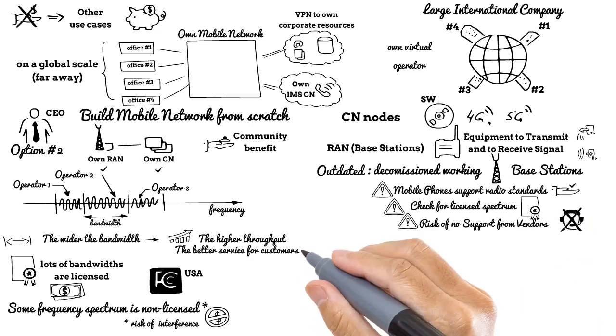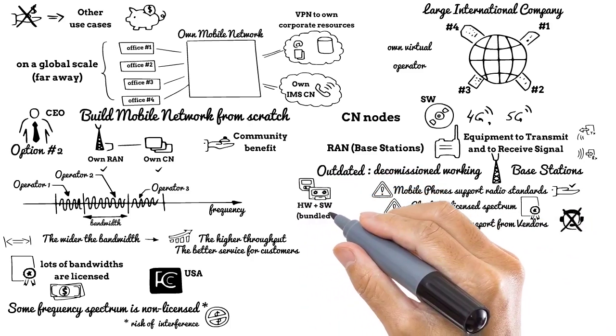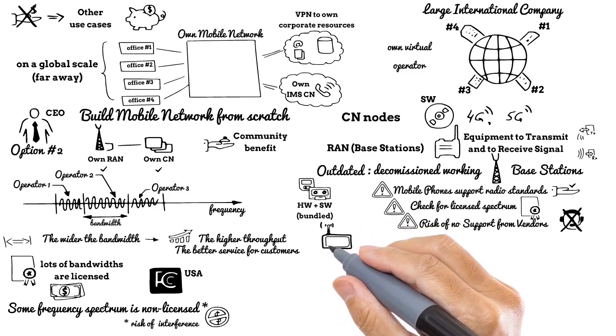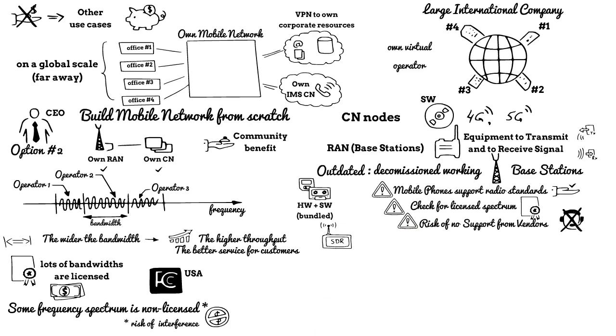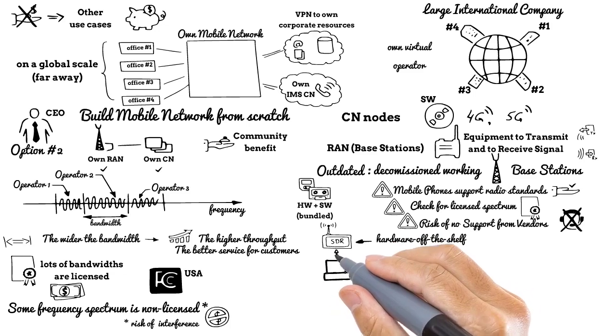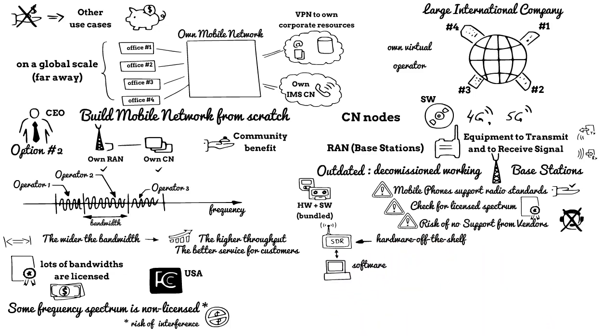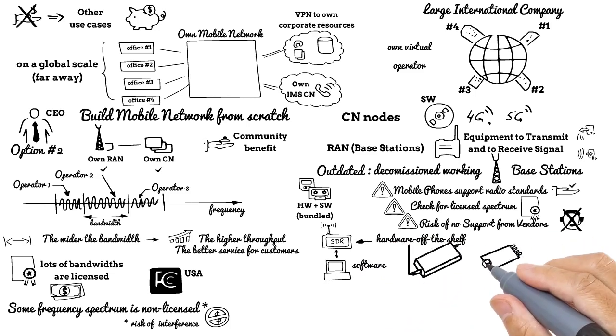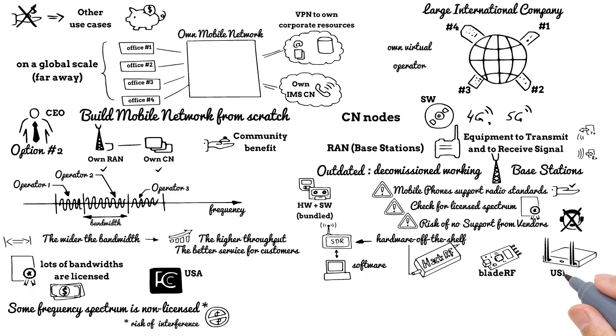There are all-style physical hardware and software solutions available on the market, as well as software-defined radios, SDRs, which are a product of virtualization, when you have radio transmitting hardware off the shelf and signal processing is happening on a separate computer this hardware unit is connected to. For SDRs, there are well-known players like HackRF, BladeRF, USRP, and others. You need to realize that most of them are for short-distance solutions. Therefore, always check the expected maximum distance, range from antenna to mobile phones. The mentioned SDR solutions may have signal strength enough to cover a few feet up to 100 or so.